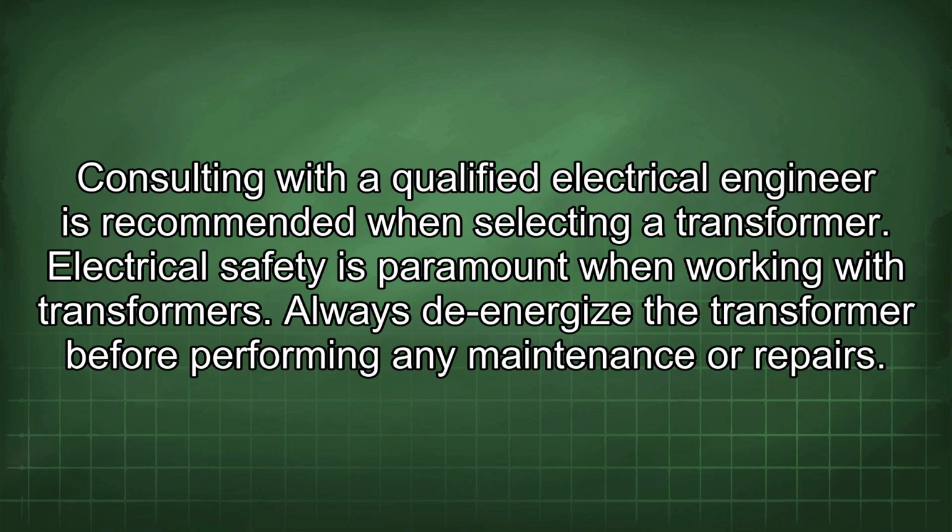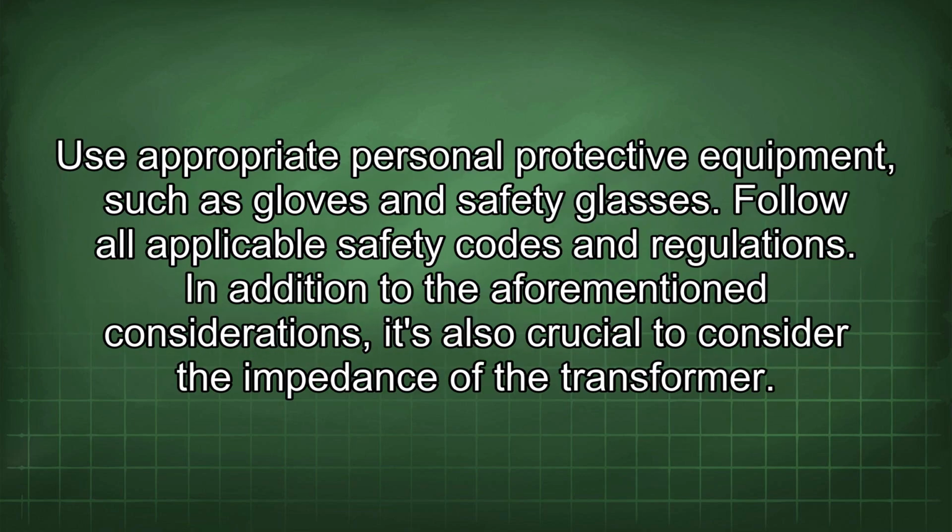Electrical safety is paramount when working with transformers. Always de-energize the transformer before performing any maintenance or repairs. Use appropriate personal protective equipment, such as gloves and safety glasses. Follow all applicable safety codes and regulations.